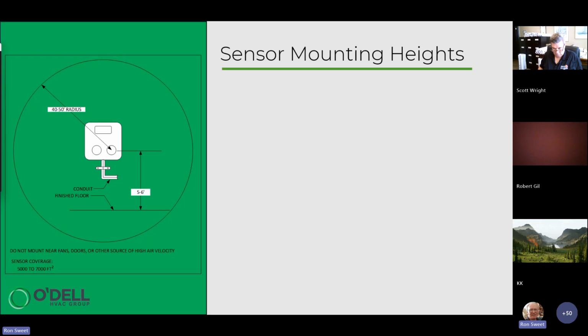Maximum allowable exposure to carbon monoxide in the workplace, 100 ppm. Allowable exposure in an 8-hour workday, 25 ppm. That's where we bring on the ventilation. We bring on the ventilation at 25 ppm to make sure that the carbon monoxide never rises above that.